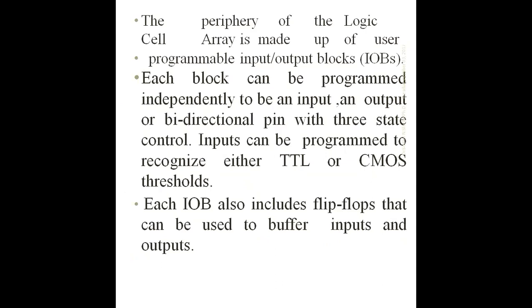The periphery of the logical cell array is made up of user programmable input-output logic. The periphery is nothing but input-output pins, input-output lines. They have to be connected to the external world. Each block can be programmed independently as an input, an output, or a bidirectional pin with 3-state control.